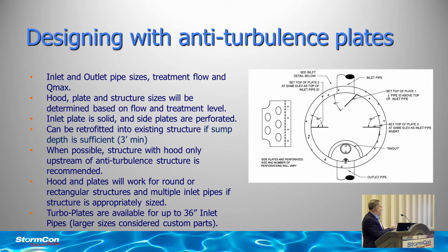So you're going to design with these parts. We can accommodate up to a 36-inch ID inlet pipe and outlet pipe with the size plates that we have. Larger pipes are coverable with custom parts, but we need to look at structures, flow, and we need to figure out how much force is going to be on those plates, because it's not an off-the-shelf sort of thing when pipes get bigger than 36 inches.